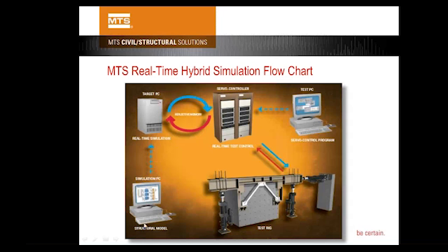So the model is created in the Simulink environment and downloaded to a Target PC. This Target PC has a very, very simple operating system. It's not like Windows and stuff like that. So the overhead is really low, and it only solves the equation written in the form of C++ code. So it solves really fast. And then the command is stored in a SCRAMNet card. So its writing is really fast, not like a hard drive or anything like that.